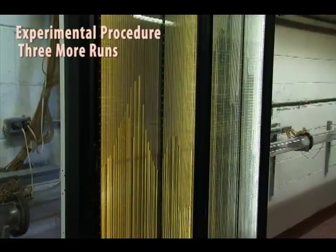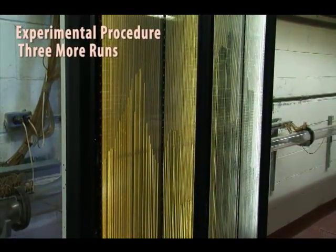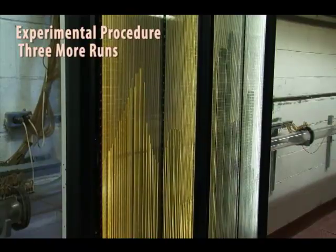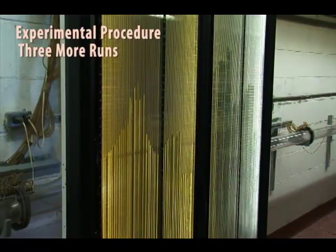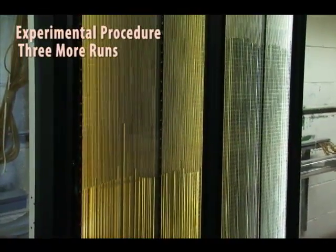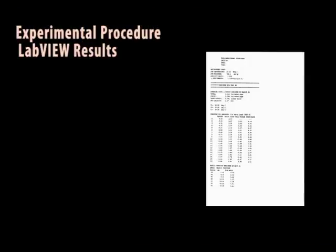Perform 3 other runs by choosing equally spaced airflow rates in between the maximum airflow in Run 1 and the minimum airflow in Run 2. After finishing Run 5, LabVIEW will finish saving and tabulating the pressure tabs readings across each obstruction device for each run.